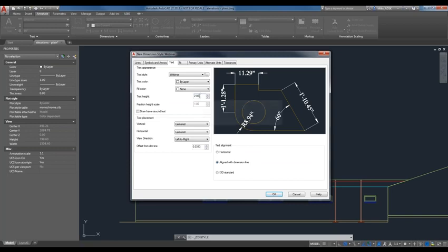We have that option available to us, but if we would have put this at another value in the text style, it would be grayed out, similar to how you see this fraction height scale grayed out. That's what would have happened here. So that's why I would recommend leaving that text height at 0 when creating your text style, so you have the freedom to change that later on in the rest of your annotation objects.